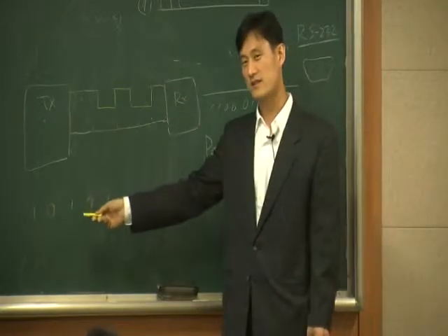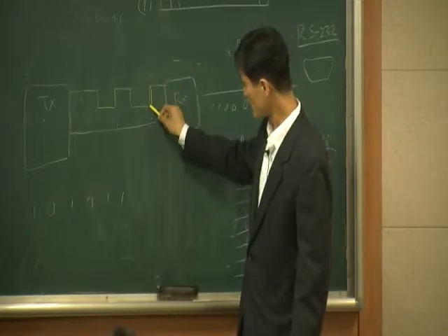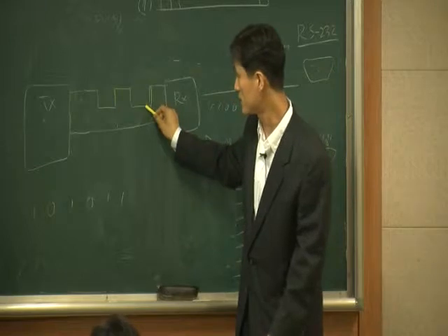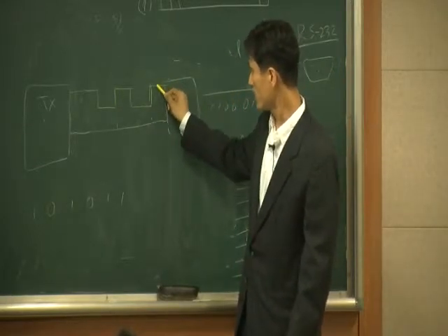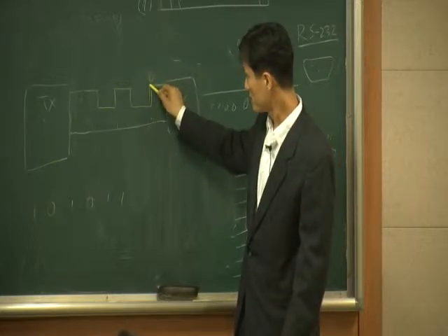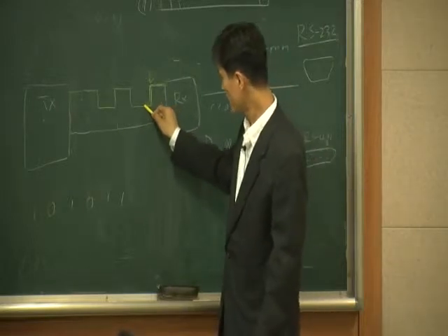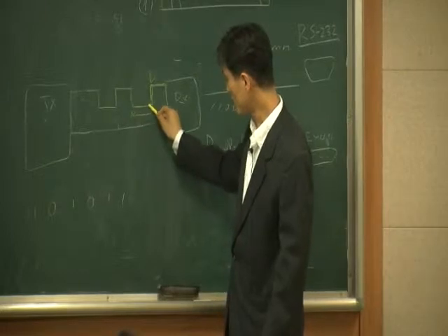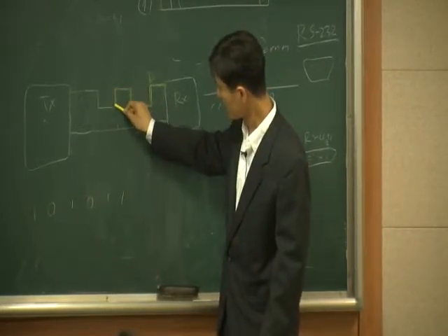can detect this because it's 1 and suddenly it drops to a ground, right? So we know this is 0 volt and this is 5 volts. So the receiver is receiving 5 volts and at this time the signal drops to 0, ground, and it stays at 0 volt for this much time and then comes back to 5 volts and a little bit later goes back to 0.